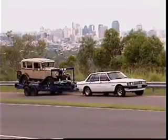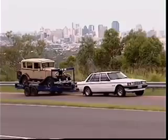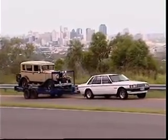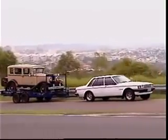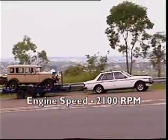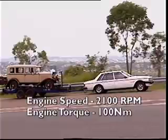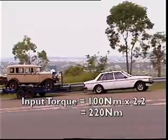Stall can be approximated to when a vehicle moves from rest up an incline, towing a heavy caravan or car trailer. Instantaneously, as the vehicle begins to move, maximum torque multiplication occurs. At an engine speed of 2,100 RPM and torque at that speed of 100 Newton meters, the torque input to the transmission will be 2.2 times that value, 220 Newton meters.